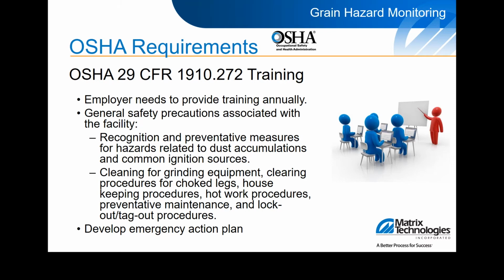Entry to confined spaces such as bins, silos, bowls, and other processing equipment needs to be detailed specifically to reduce engulfment and mechanical hazards. Permits must also be used for entry of such bins and also when performing hot work in grain areas. Permits are required to cover any hazards dealing with grain.